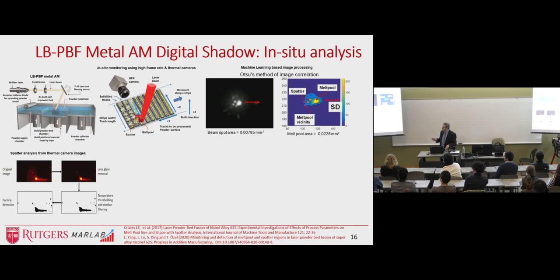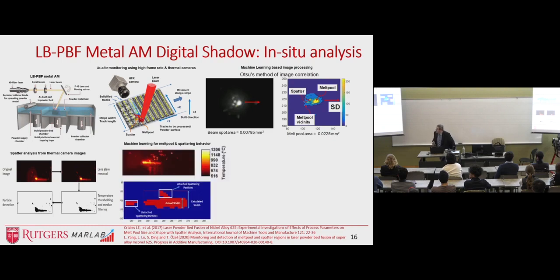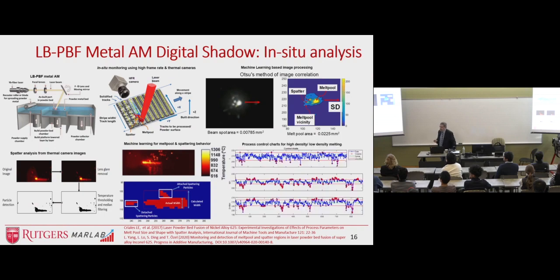And we can actually look at statistically how the melt pool dynamic is changing. Through the thermal imaging, we can actually look at the thermal original image and clean the glare in the lens, and also apply machine learning to convert the shape analysis. We can actually find the amount of spatter that is taking place in this case. So this is a thermal camera result. Through machine learning, we can actually obtain statistically whether over-melting or under-melting is taking place.